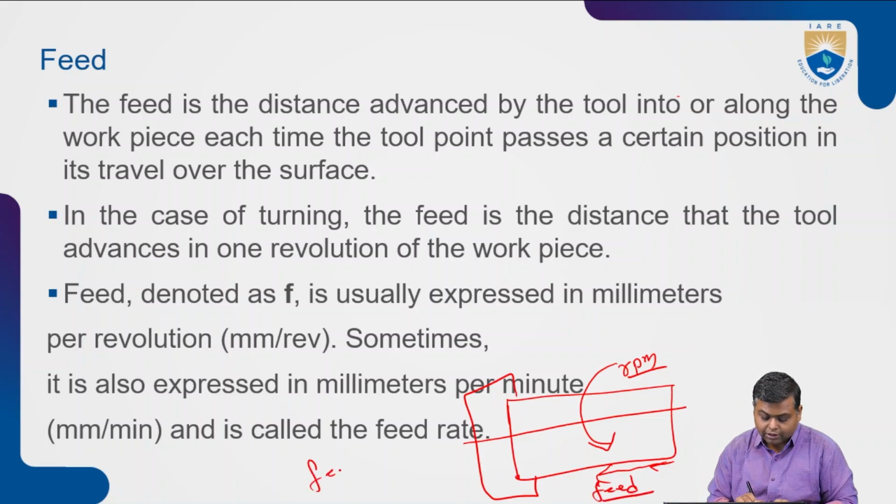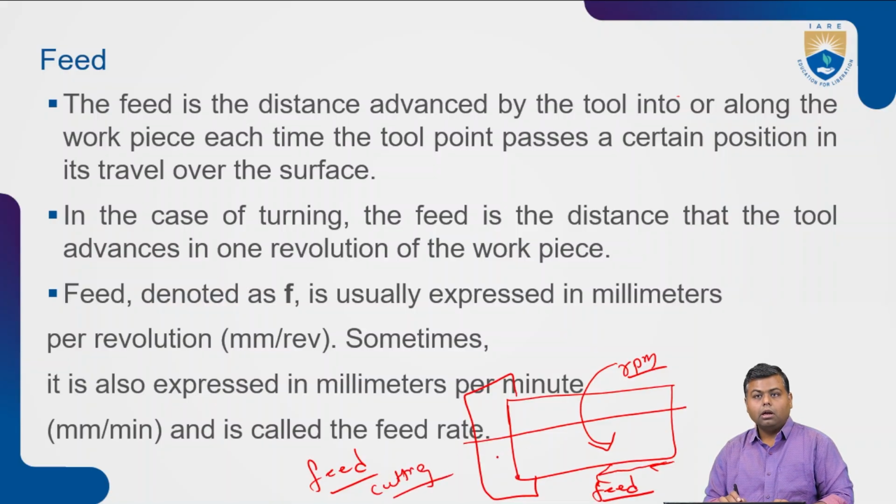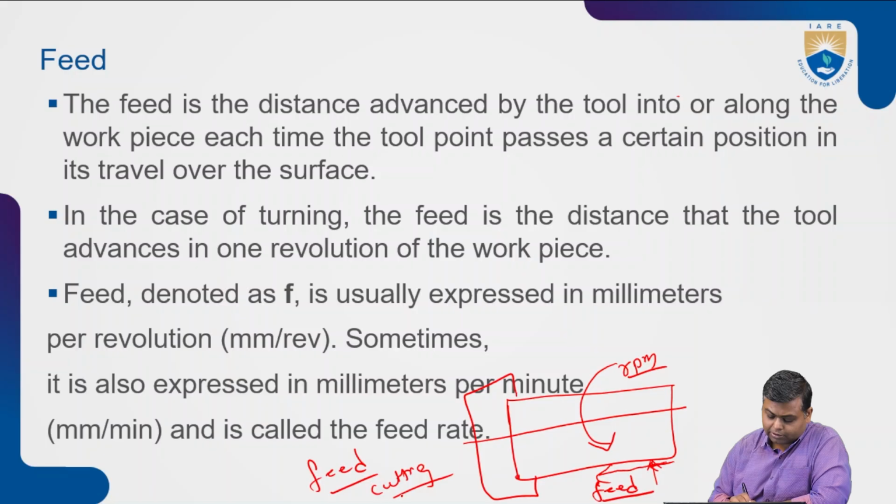So feed is very different from cutting speed. Cutting speed is how fast the movement of your workpiece is getting into contact with the tip or edge of the tool. But when it comes to the feed, it is the advancement of the tool for one revolution of the workpiece.